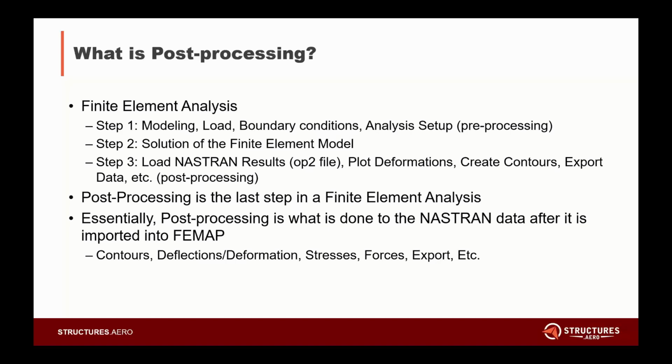Step two is actually solving the finite element model, solving all the equations, the stresses, and what output you're actually looking for. And that actually happens external to Femap. It happens in Nastran. They're two separate softwares. Step 3 is actually loading in the Nastran results, which is in the form of an OP2 file.